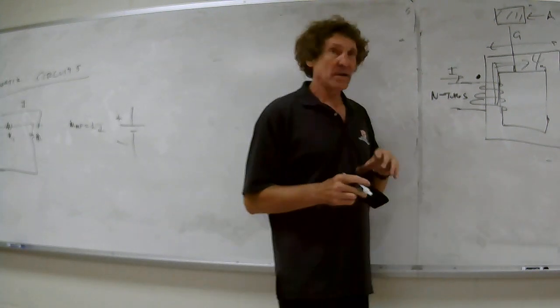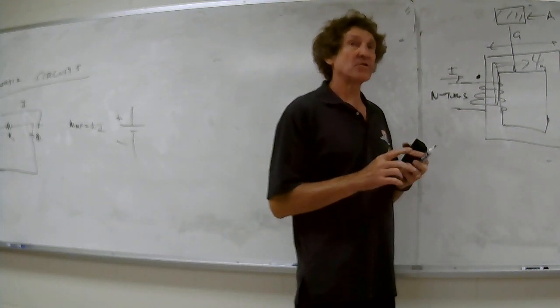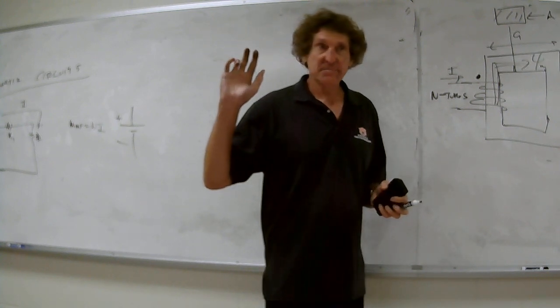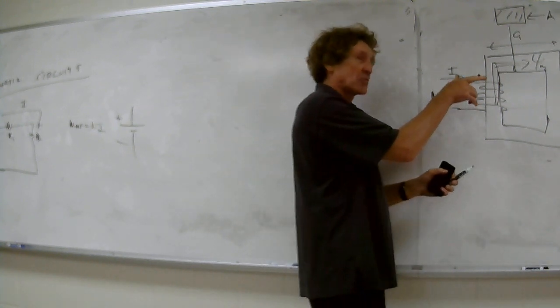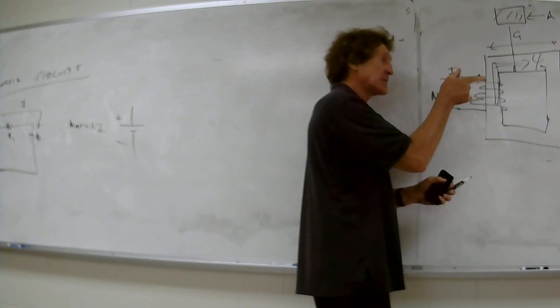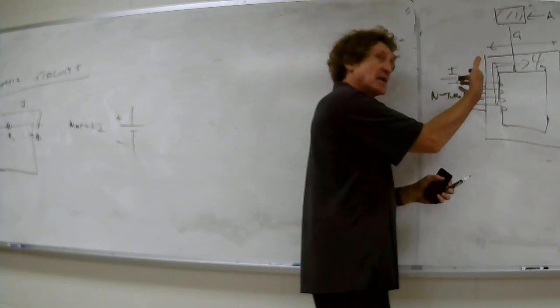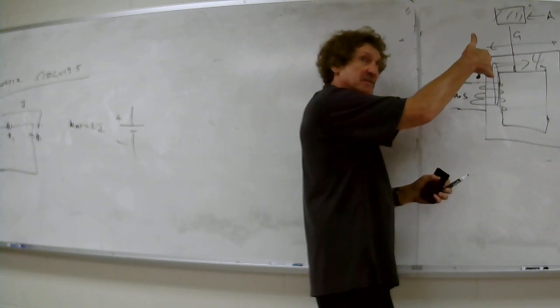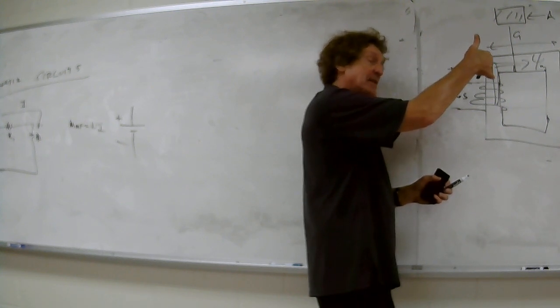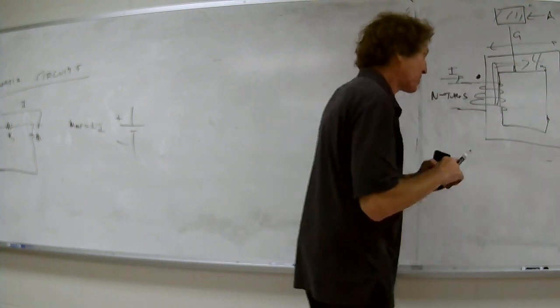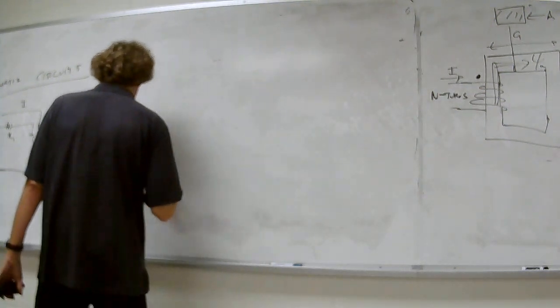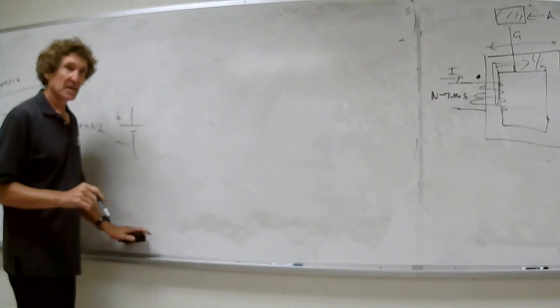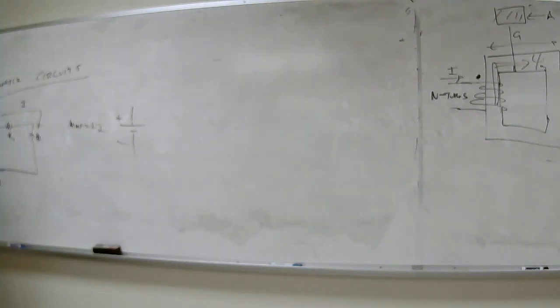Now, that dot shows you the polarity of the direction of current. Y'all have right hands. You take your right hand, grab the coil of wire such that your index finger points in the direction that the current's flowing. You see your thumb? That gives you the positive sense of the actual magnetomotive force, or the direction positive flux will go. So it's like this. This is MMF.